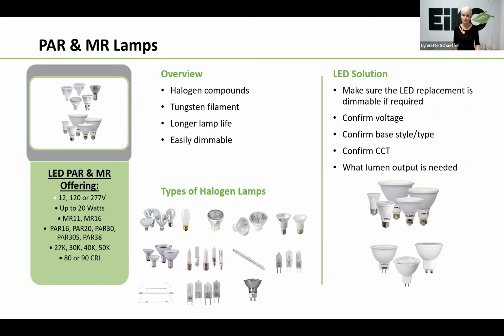All LED lamps, as I mentioned, have a driver, or in some cases, maybe they can utilize the existing fluorescent ballast. However, they have to have some kind of driver, right? And also, not all LEDs are dimmable. That's one that a lot of people just don't understand. So if you've ever bought an LED lamp and you get it home and you try to dim it, you're like, why aren't these dimming? It may be because you bought an LED lamp that wasn't actually dimmable. It has to say dimmable on the package.